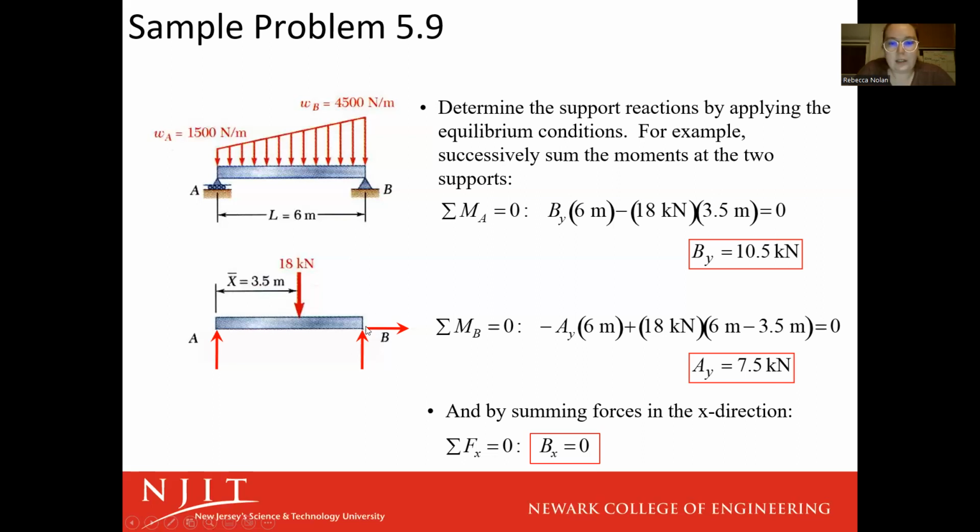By is going to be acting in the opposite direction, so that's going to be a positive rotation. And we don't know the magnitude, but we do know that it's acting at a perpendicular distance of 6 away from point A. With arithmetic, we can get By. From there, we could do summation of forces in the y direction to get the other forces. I think I just wanted to show that you could do the moment about either point and get a solution.